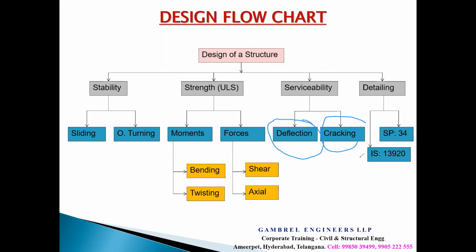And the cracking criteria, in a sense, we also have to ensure that the members are not getting cracked. This cracking criteria is more important, especially when we are dealing with water retaining structures. It can be sumps or it can be dams, right? Where a structure is dealing with water or in contact with water, cracking criteria is more important.